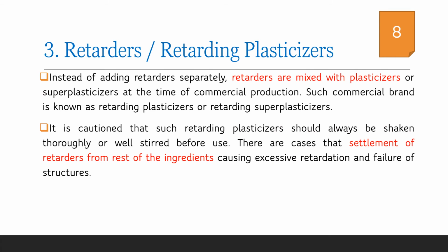Retarding plasticizers are retarders mixed with plasticizers or superplasticizers. Care should be taken that the retarders added with the plasticizers may settle down, and hence we have to shake well before it is used. Otherwise, these ingredients may cause excessive retardation and failure of concrete structures.